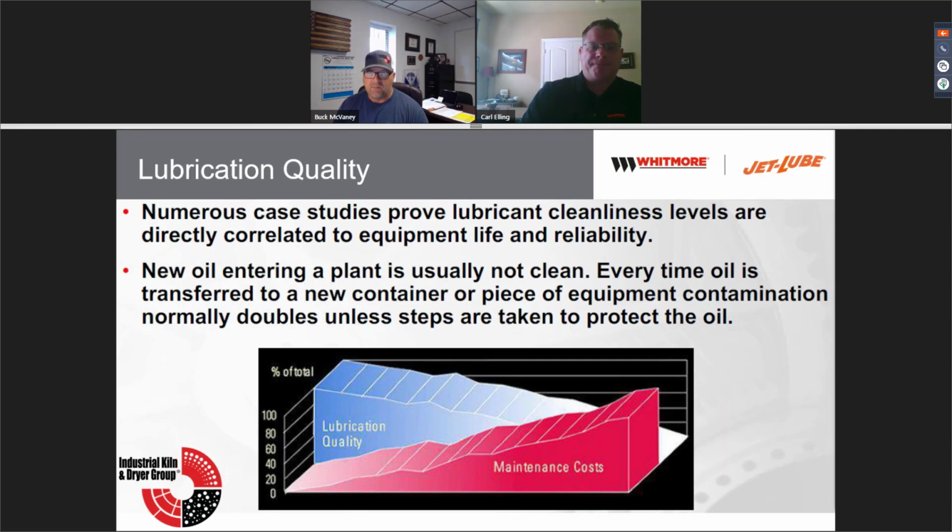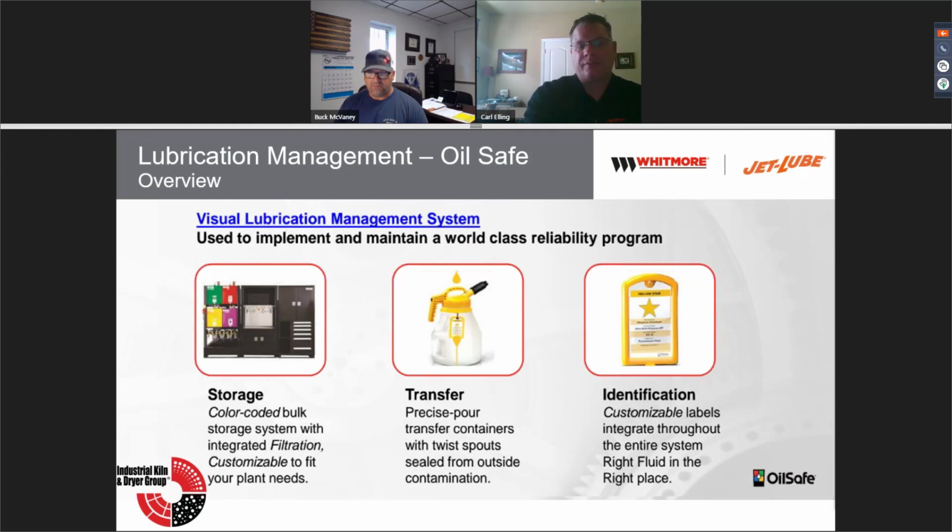Yeah, and one key thing, just to share with everybody, I've been in lubricant sales for quite some time. Just know, new oil is not exactly clean. We all assume it is. It's been filtered. It has a certain ISO cleanliness level. Well, guess what? The only people that have a say in handling and managing the cleanliness are the people at the plant. And you can go back to this particular slide. Using this particular system and this method will help not only filter, because you've got three-way filtration on this one. You filter oil going into the tanks. You can do kidney loop, and you can filter coming out. So it's a great way of managing and filtering your oil as you receive it into the plant, because you are the last line of defense.